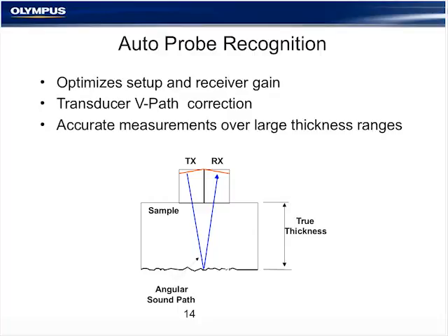And that's kind of what we're showing here in this diagram. If I get my laser pointer, my faux laser pointer here. Any dual probe, or certainly most dual probes, are constructed with two crystals, a transmit and a receive, that have what we call a roof angle. And due to this roof angle, the sound actually travels through the delay of the dual probe and enters the part at a very small angle, typically just a few degrees.